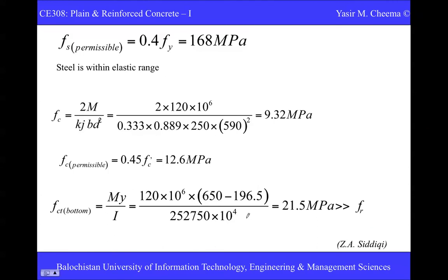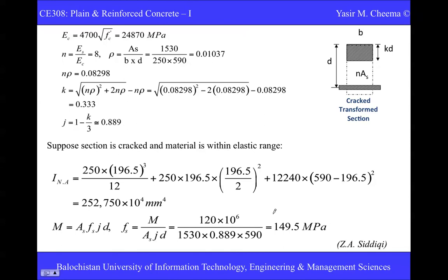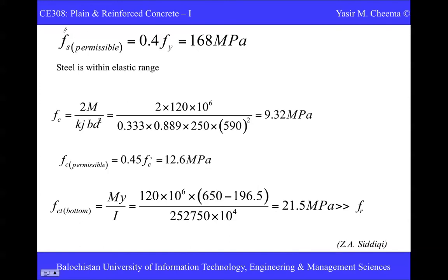So moving forward, the stress that we calculated is the stress developed due to the given geometrical and loading conditions. Means geometrical conditions, the location and all the stuff of the sections, then we have material properties given there, and then the loading. Because of all this, this is the developed stress over here in the steel. But here this is the permissible stress, this is just a code value. That means the ACI code recommends that steel can take maximum stress to this level.